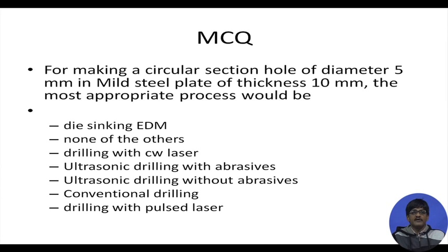It's not specified how this drilling is being done, but without abrasives, you'll be at a disadvantage. Whether some other kind of material removal method is being employed or not, it's not clear. It might be that you won't be able to cut at all if you're using a conventional ultrasonic drill without abrasive.